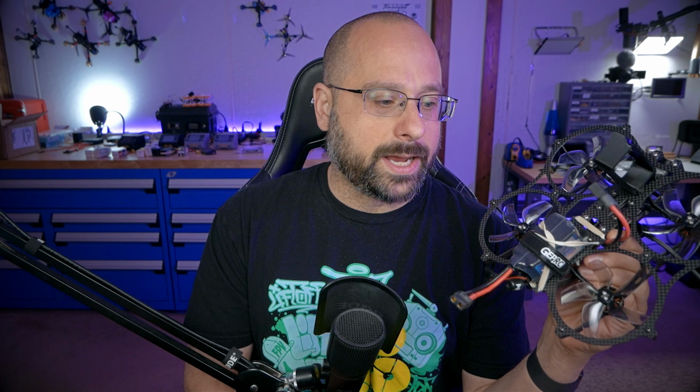And amps is relevant, current is relevant, because the more current you're pulling from the gas tank, the faster it's going to be empty. But in addition, each battery has a certain C rating that relates to how many amps you can safely pull from the battery. So if you know you've got a battery that's rated for 70 amps, you might be interested in knowing how many amps your quadcopter is pulling at any given time to see if your battery's C rate is adequate. But that's not actually the main reason to care about current reading.